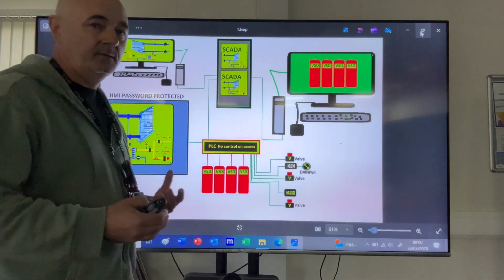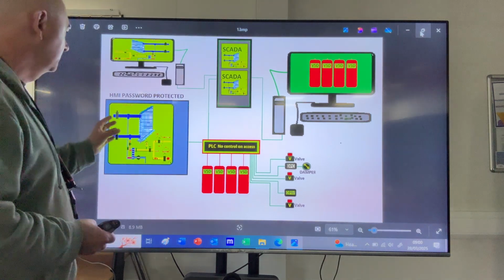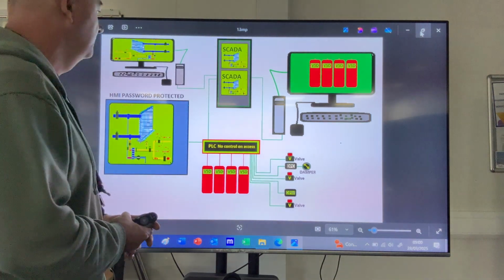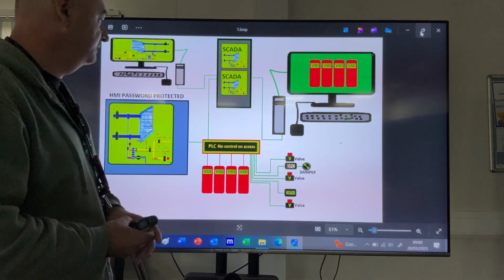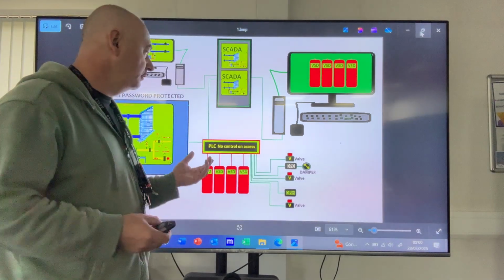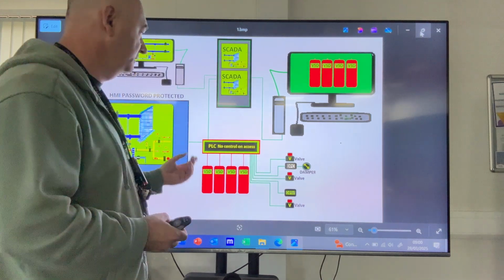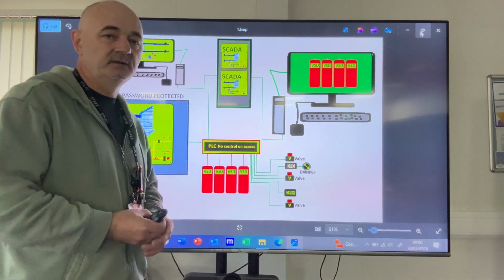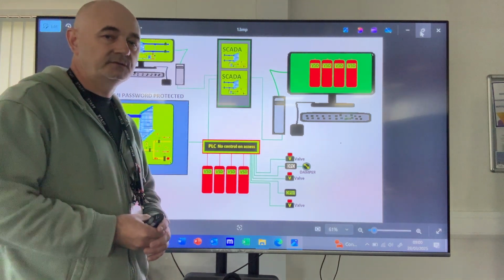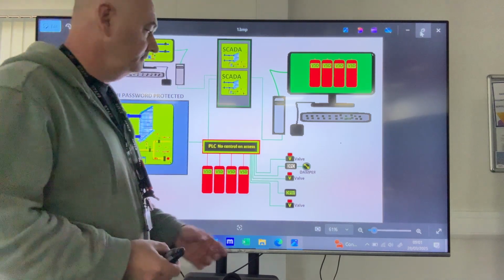This is something which probably has to be debated with IT. We have the human machine interface, which is password protected. We have the SCADA, which is password protected. We have the client, which is password protected. The PLC is supposed to be secured, but anyone with a laptop can plug into the PLC and change the set points. The PLC is not passworded, and the variable speed drivers also don't have any passwords. Someone can go and change the software of the variable speed drivers. We have a lot of back doors.